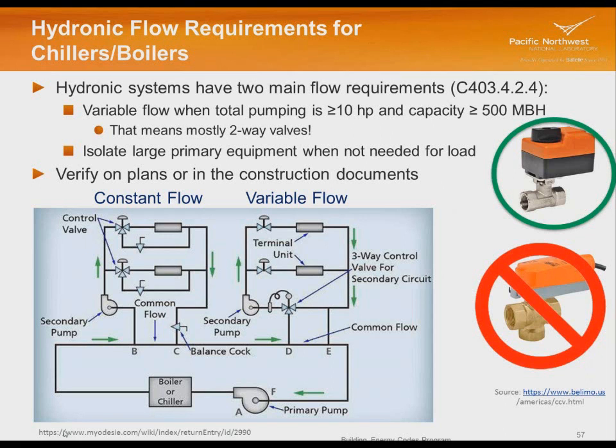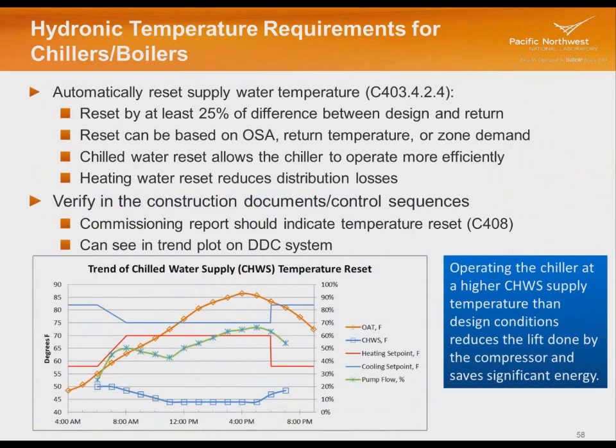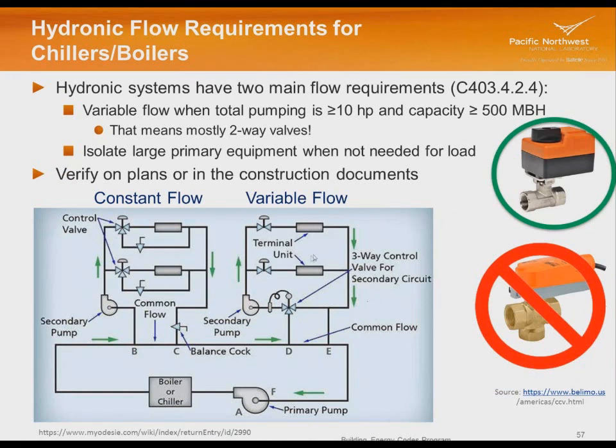We can kind of look at a graph through time with these units. One thing I did want to mention here as well. Now we might have, say, one three-way valve at the end of this system, so we might have 75% two-way valves and one three-way valve out here at the end of each long pipe run, so that the water gets out there, and so that when we get to a really low load condition, we still have a minimum flow that our pump needs to have to not go into a high head condition.